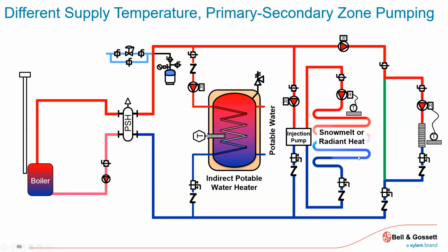No, because that is just like a closely spaced set of tees. So the flow that will be occurring will be a function of if these guys happen to be still calling. But if he's off, the only flow is going to be whatever the GPM is. So this pump's doing his thing, then all of a sudden this pump is running and he's taking X number of gallons a minute. So he injects X, an equal amount of hot water is now moving in this direction, but it can't go here because it's trying to get to the suction of that pump.